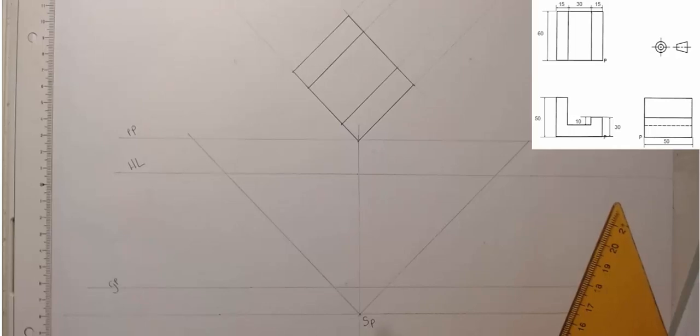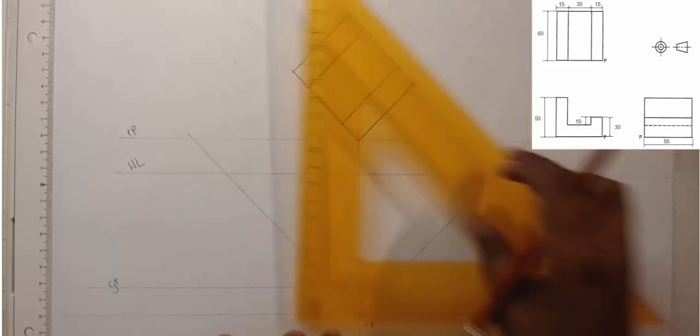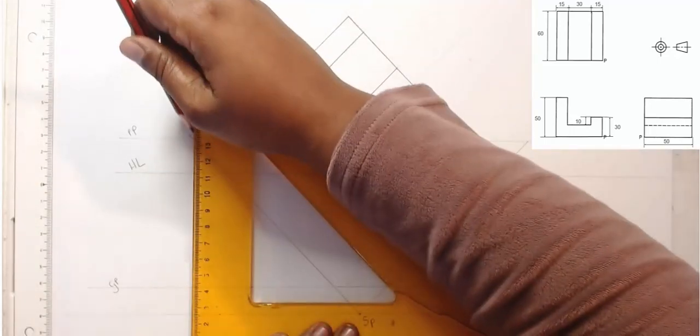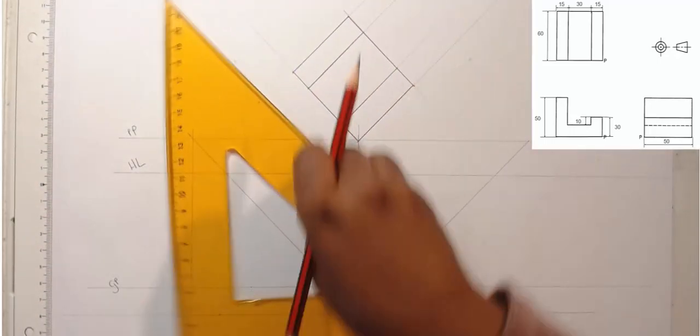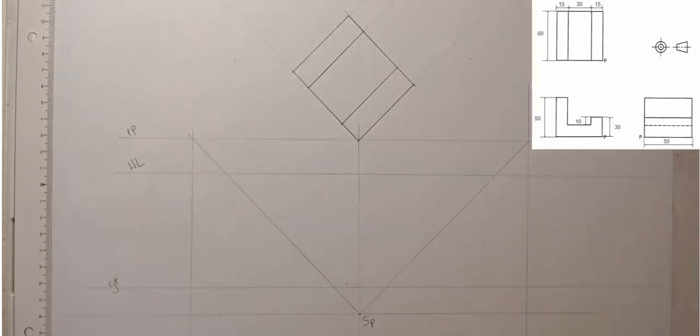We then draw two perpendicular lines. Okay, two perpendicular construction lines from where the lines intersect on the picture plane. So we're going to draw perpendicular lines all the way down that part, and also here all the way down. Okay. Then from there, what do we do? Now, these lines, when intersecting the horizontal line, will give us the right and the left vanishing point.